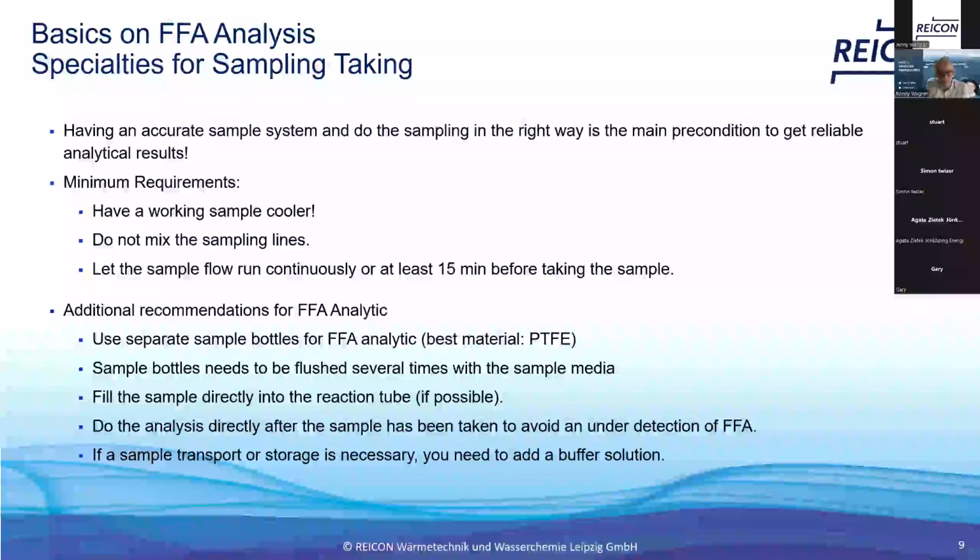The best material is PTFE, because it is less affected by film formation, and so you get good results. As the sample bottle will also be covered with a film, you should flush the bottle several times with the sample media to get a pre-treatment of the sample bottle surface.